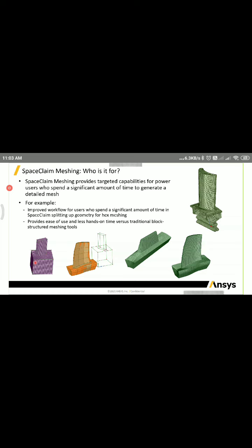So I can define the mesh in such a way that the number of edges or number of faces which I'm going to associate over here for my template, or whatever part names I'm going to use for the template, I'll make sure that everything is mapped so that the blocks which I generate for the template can fit into this to generate the same mesh.